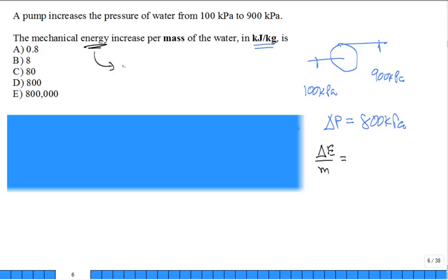It's either through an increase in the kinetic energy or the potential energy, or this flow work energy, this mechanical flow energy. All right? Was there an increase in kinetic across the pump? No. Potential across the pump. The only thing it did was increase its flow energy realized by an increase in pressure. It seems so trivial, but it's not trivial.